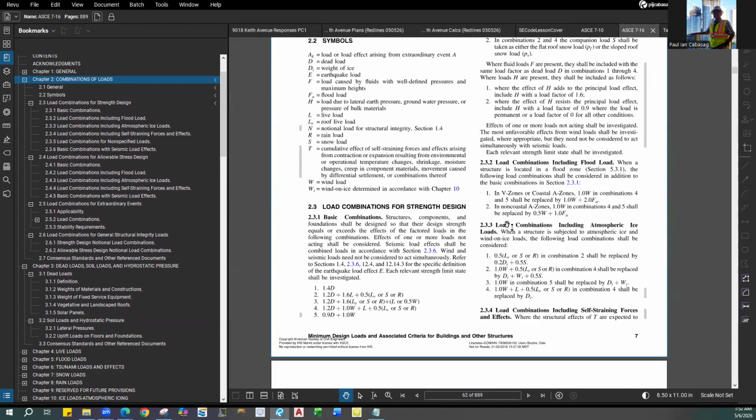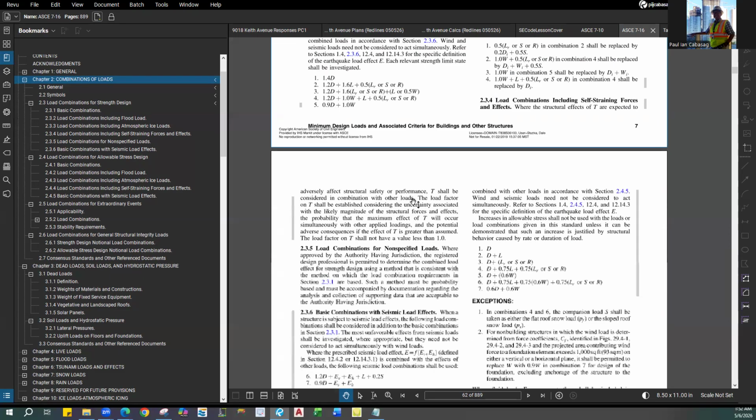So when you're doing the design, typically you do gravity, and then you do lateral, and you do foundation. Gravity is usually a vertical type of load, like a dead load, a live load, a roof live, snow load, rain load, which are the loads that you see here.